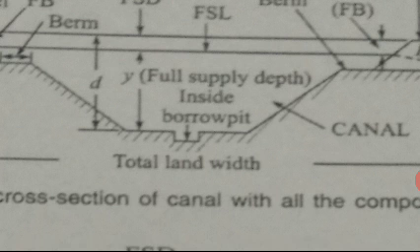In the bed of the channel, the borrow pits may be located in the center of the section with their maximum width equal to half the bed width of the channel and depth not more than 1 meter. In between successive borrow pits along the length of the channel, a minimum distance equal to half the length of the borrow pit should be left.